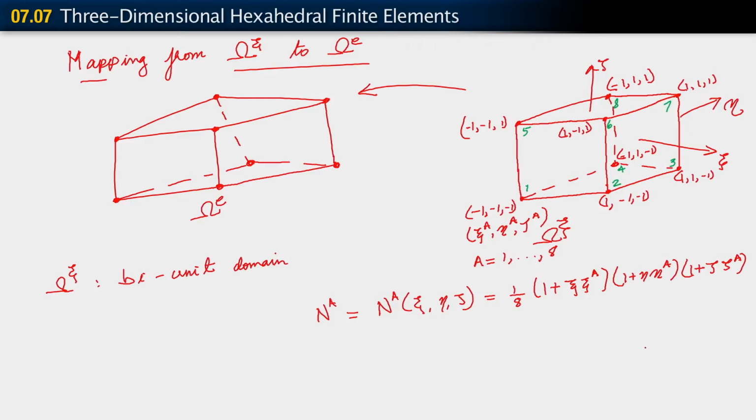If you look at this form, what you will notice is, if you also recall the way we wrote out our Lagrange polynomial basis functions in 1D, right? In 1D, we had only one of these contributions. Okay, here in 3D, we have three of them. It's just multiplied together, and this particular way of constructing our basis functions is called a tensor product approach.